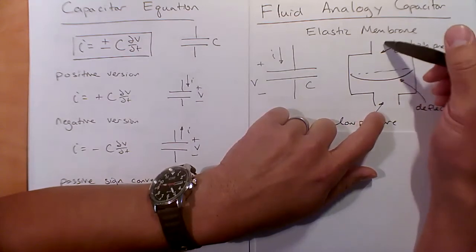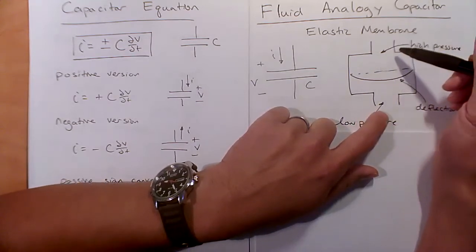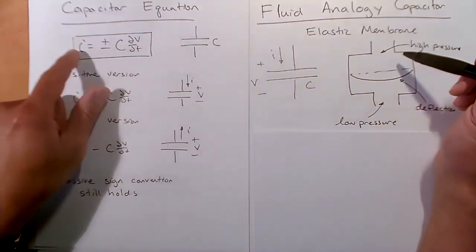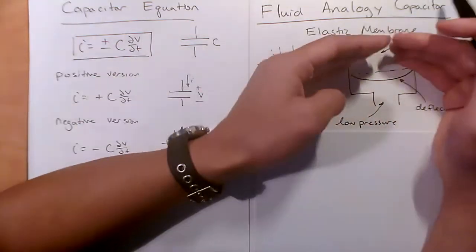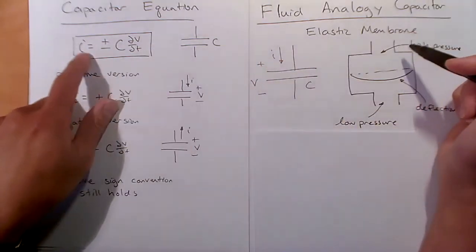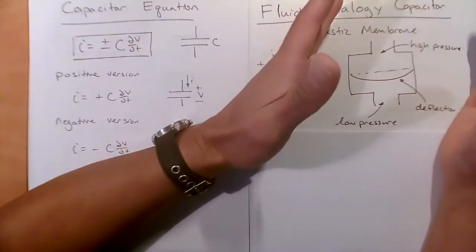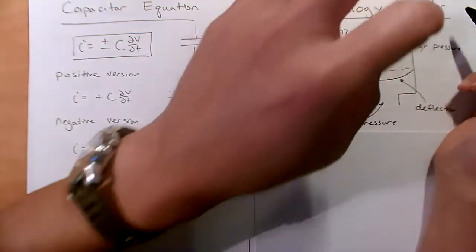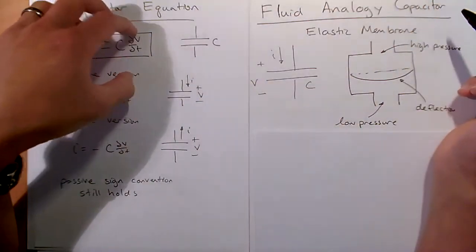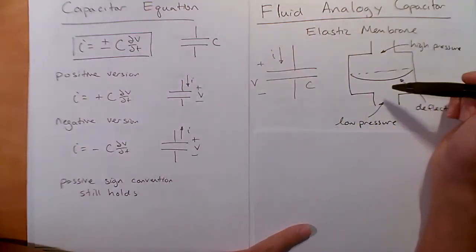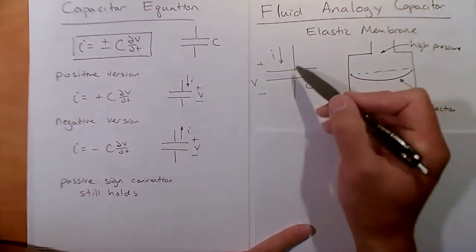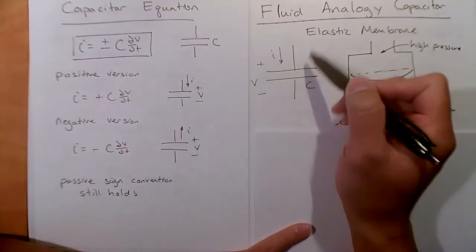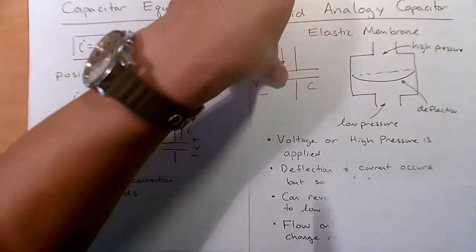And so once this pressure, I don't want to say equalizes, but becomes steady state, now this dV/dt goes back to zero, and then the current shuts off, right? So you get this small little blip in current, right? Just as you're filling up, and then it goes away. So I hope that helps lock in what this equation means in terms of our physical intuition, all right? All right. Now, of course, the electrical is different. You're building up charge and then can release charge, but this is our hydro analogy. Okay.